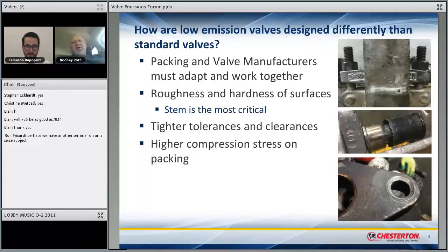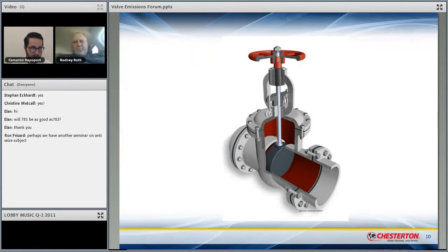So if you hear that, you know that they're talking about the actual flange. When they say gland flange, they're talking about the pieces actually tightened to compress the gland into the packing. Yeah, so you can maybe see it a little bit better here. Can't exactly zoom in, but this flat part on the top that your actual studs go through, that's the gland flange. The cylindrical part that actually enters the stuffing box is the gland. Then you have your packing inside the stuffing box right there.